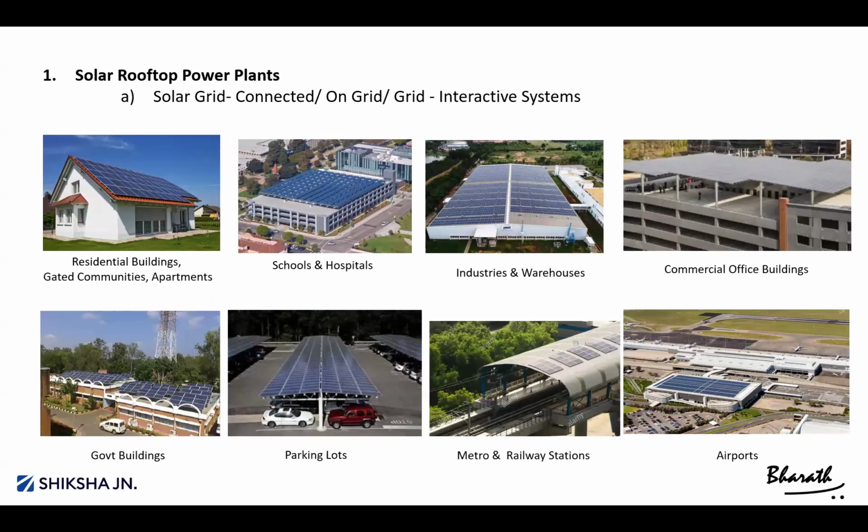So you can see rooftop systems where we can set up. Any rooftop with a proper grid connection with one energy meter, a government energy meter. So wherever you have a roof space, shadow-free roof space, and you have a power supply connection, then we can set up a grid connected system.